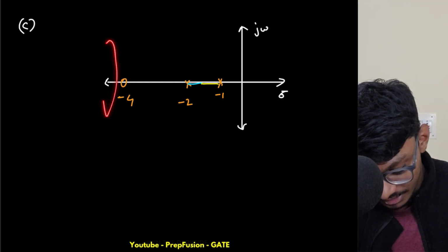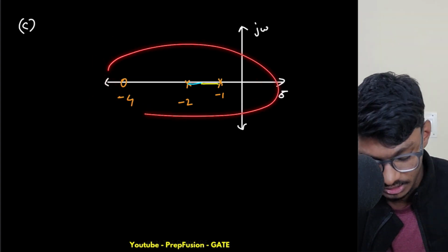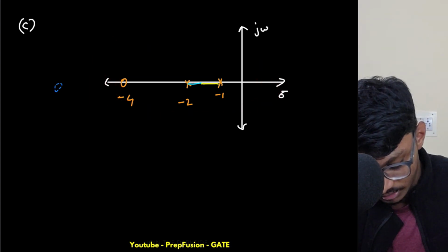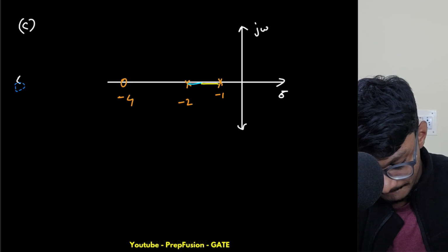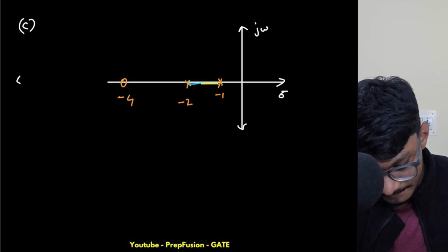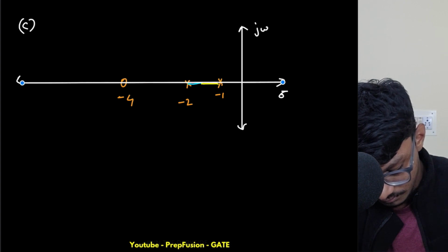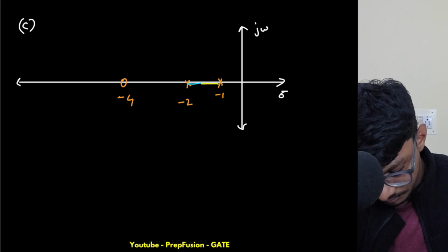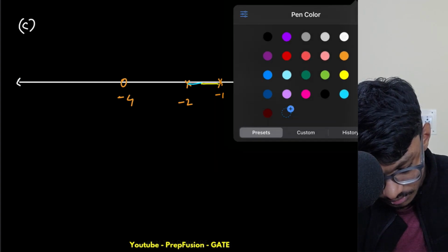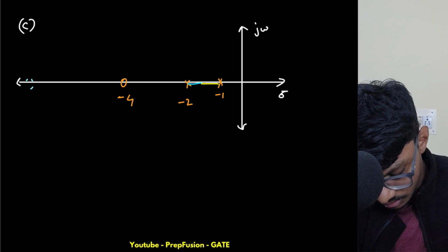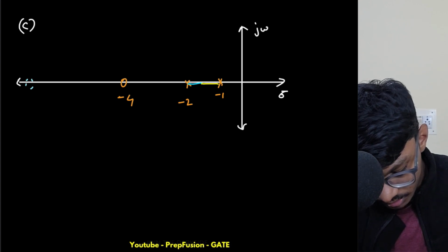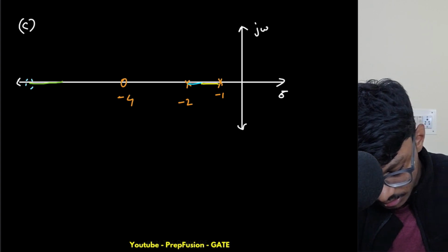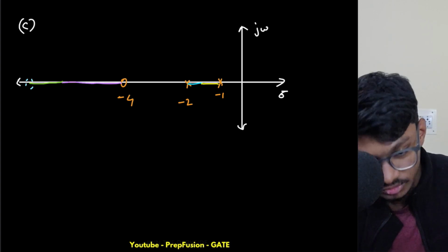So now, this is a valid point again because the number of poles and zeros are odd on the right hand side. So again I will extend this. So here I'll have a virtual 0. So if I have a virtual 0 around here, this one will go from here and this one will go from here. Now we have a break in, so we are patching up now.